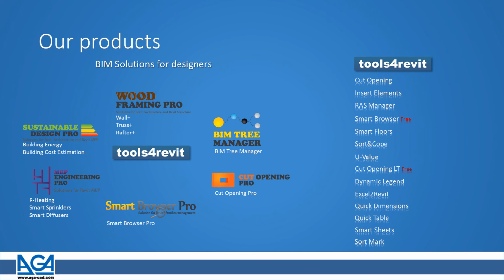Cut Opening allows users to automatically create openings in elements such as walls, roofs, floors, etc., where ducts, pipes, cable trays, and conduits intersect them. Smart Browser Pro is designed for quick and easy search and management of Revit families. For example, you can copy families from one project to another using the drag and drop function, and it's a must-have for all Revit users.